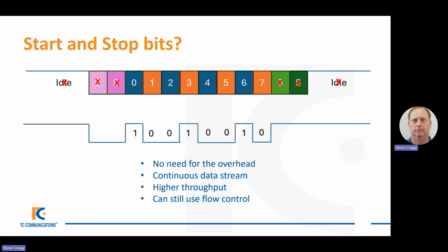So do I need start and stop bits? Absolutely not. I don't need the idle between the bits. I don't need the start bits. I don't need the stop bits. I don't need to go back to idle at the end of it. So inherently, you can see by just taking that overhead off, it's a great deal more efficient.